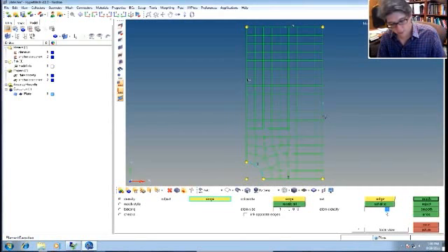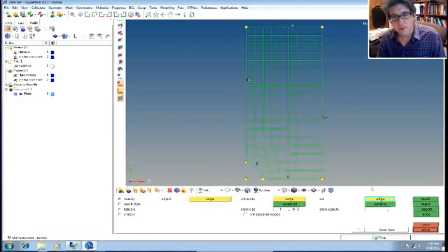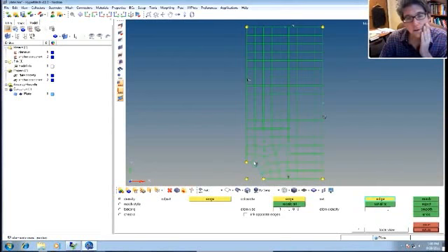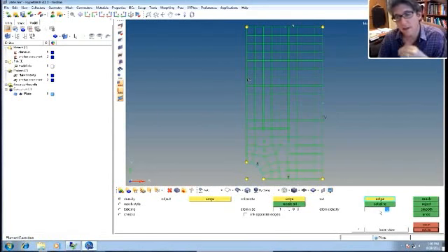That was set to 3. Let's make this more like 5. And I'm going to set this edge to be 5. So now it has 5 nodes here. You can see how that mesh will look. So it added some more elements on here. I can control it, so you can control things that way. It's actually kind of nice. Actually, maybe that isn't even enough.